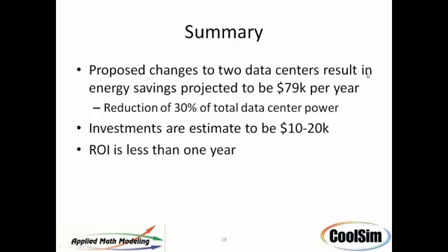They just have the evaporator in a different location. The DX unit exposes the evaporator to the data center. A chilled water-based system has the evaporator outside and uses a cold water loop between the evaporator and the data center itself.